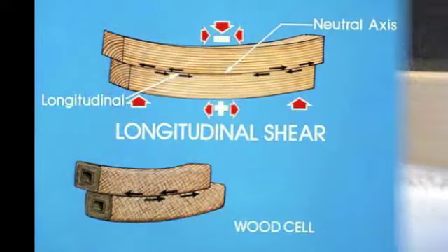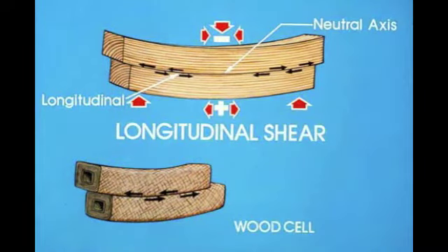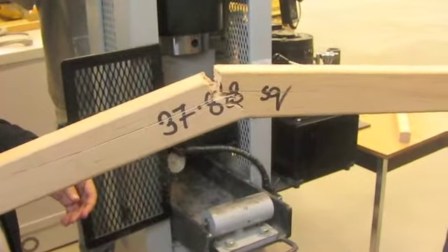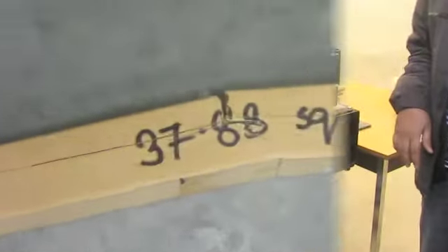Notice the bending action occurring in the beam. This causes a lot of internal forces, as we learned in class. The forces look something like this. Now, if you take note of the failure that has occurred, you'll see a lot of similarities. The tensional failure at the top, which was on the bottom, and the shear failure right in the middle.